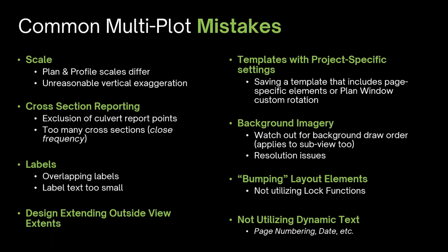So my final piece of introductory content, I did want to highlight some of the multi-plot mistakes that we most commonly see and we get a lot of support inquiries based on. So one of those is regarding scale. Often we'll see multi-plots that have a differing scale between their plan and profile. So that's something definitely to watch for, or multi-plots that use an unreasonable vertical exaggeration.